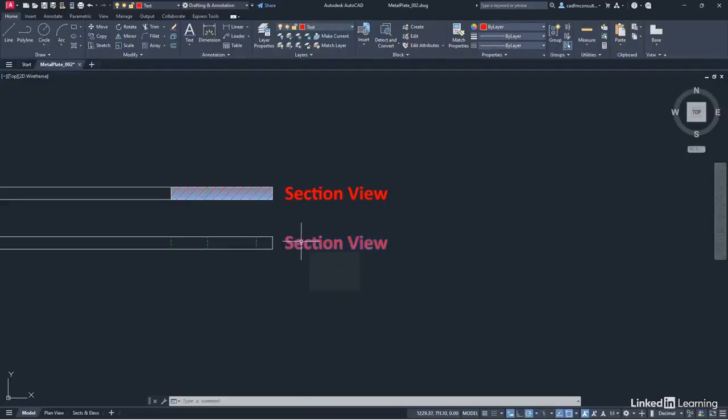So we double click on the text. That will allow us to edit the text. This is our side view. So if I click in this highlighted text box now, I get a cursor and I can use my keyboard, backspace there, type side view, and then just click outside the text, and you can see there that that updates accordingly.